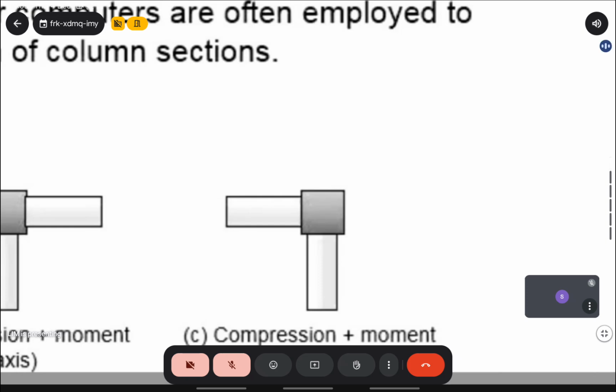So the beam at the bottom, there's no beam to counter it at the top, so it's going to cause bending in that direction. And then there's a beam on the left, which is not balanced by a beam on the right. So it's going to cause bending in that direction as well. So you get bending in both axes now. So this is sometimes the worst case for bending.